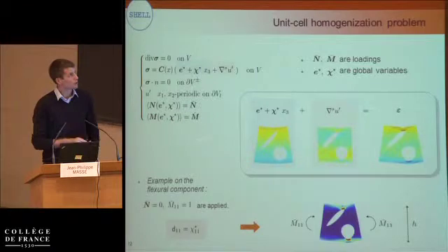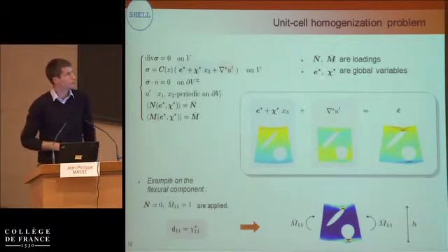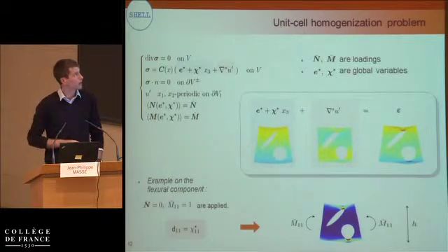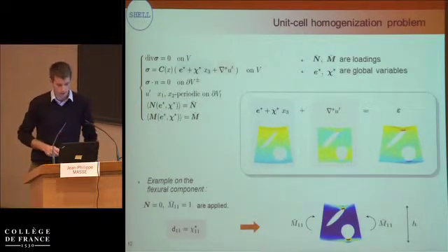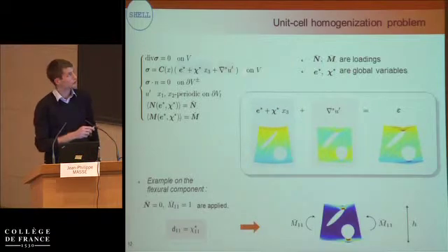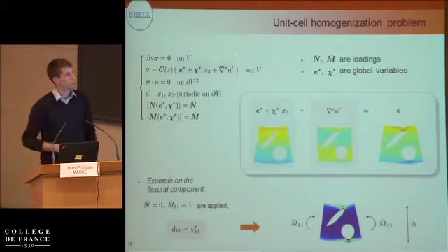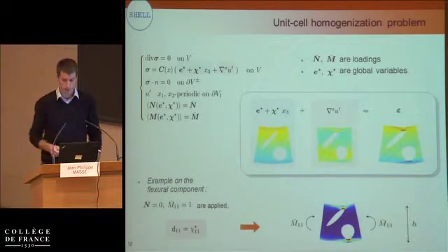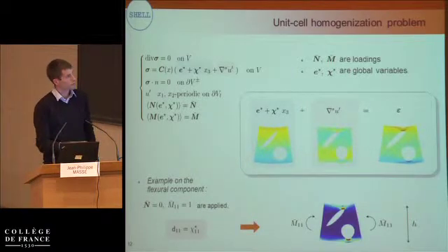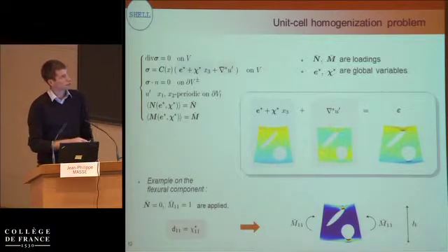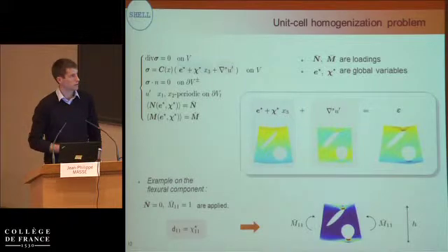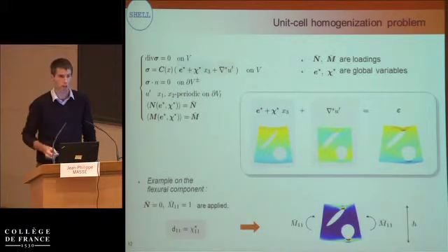This is done through global variables implemented in the strain expression, so that the unknowns of the problem are not the displacement or the strain, but the perturbation of the strain with respect to the homogeneous deformation of the unit cell. So the global strain of the unit cell is the sum of this homogeneous solicitation and the perturbation due to the architecture.